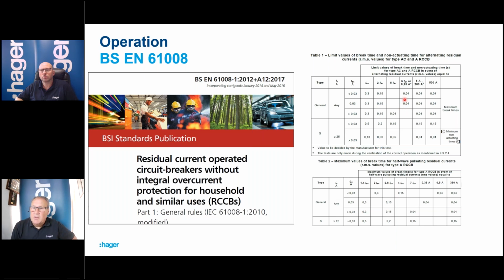Unfortunately, I'm going to apologise here again. Anyone remembers our RCDs we brought out when the 18th edition regs came out, when we brought out our new RCCB to cope with 100 milliamps for the overload protection of the consumer unit. Okay, we actually coordinated them for 250 milliamps because it was allowed by the standard. So apologies again for that. If that caused anyone any problems, we have corrected that obviously years ago now.